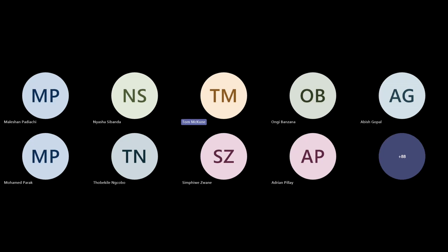All right, thank you, Adrian. And then the Mzimkhulu River Bridge, was there a difference in the damage between the beams supporting the roads and the ones supporting the rail? Hi, Tom. Good man. Thanks for that question. So in a nutshell, the main girders, the answer is no. There weren't any differences in terms of damages to the main girders, the longitudinal members.